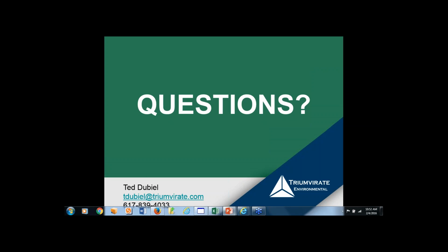And here's a good follow-up from Emily, I think. When identifying potential peroxide-forming compounds, how can you safely discern if the chemical is safe to open and test on-site, or when is it necessary to remove and do off-site? Any of the testing we're going to do on-site would just be a difference of whether it's done within a lab or outside in a parking lot. That testing is going to occur prior to any of the material being removed from site. So part of it is storage, age, whether it's inhibited or not, and how the material looks. Like the pictures in the presentation of the solvents that had visible solids in them, those were all ones that we remotely opened.